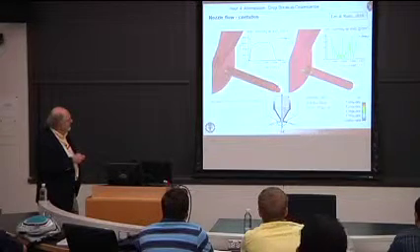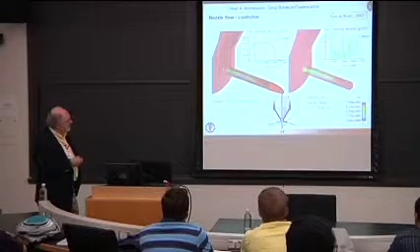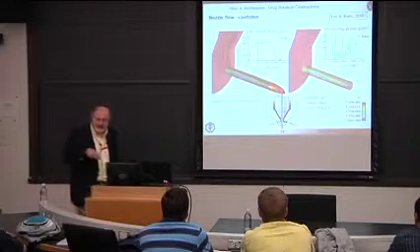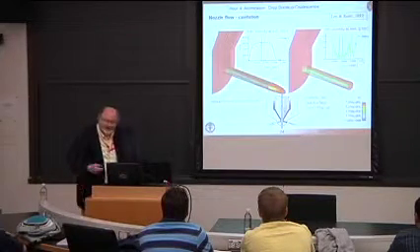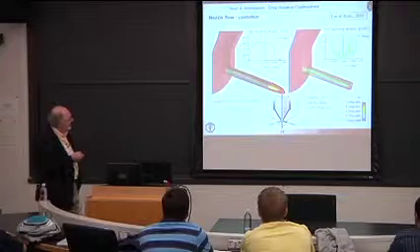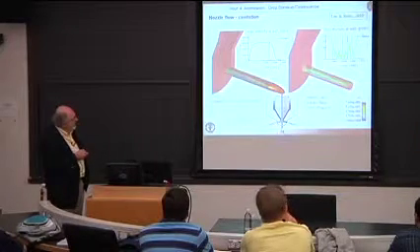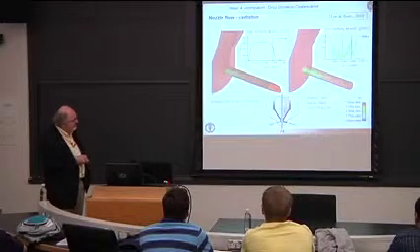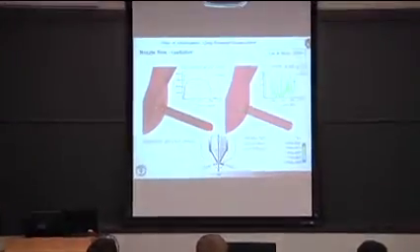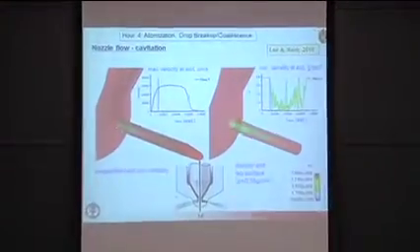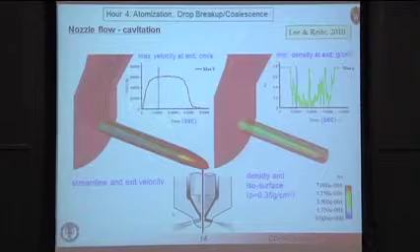Notice that you see all kinds of really interesting flows. It reminds you of what happens when you let the water out of the bath, right? As the flow goes down the drain. And that's what you're seeing here as the flow starts up. You also notice that these cavitation regions, which show up here as low-density regions, appear first at the corner of the inlet of the nozzle, and then they extend all the way downstream.